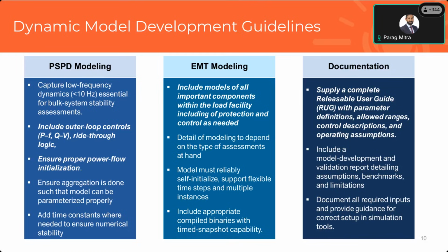Again, be very deliberate about the kind of assessment you're working on and develop the model to that detail, because having a very heavy model doesn't really help. It just takes a lot more time and doesn't provide significantly higher insights. And if you have certain compiled binaries, make sure that all those appropriate compiled binaries are included, and you have some time snapshot capability so that you can start these simulations from a certain point and keep running them, just for optimization of your time.